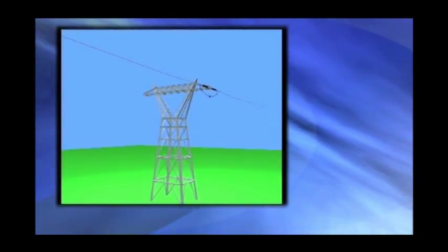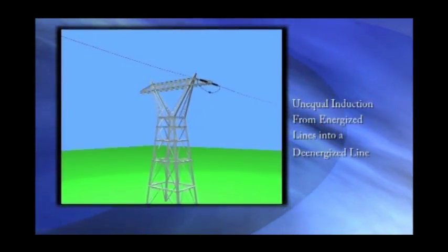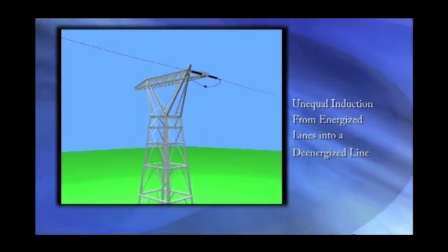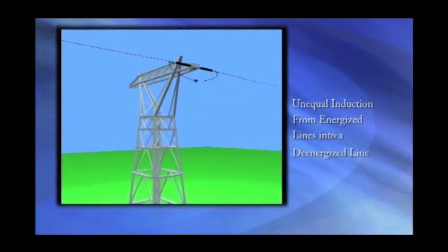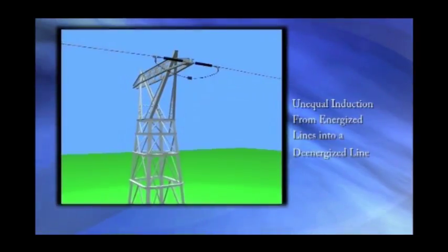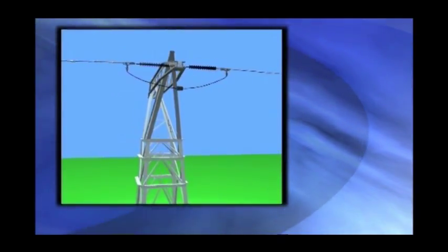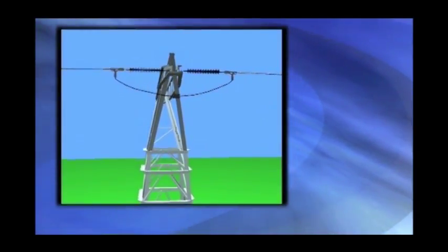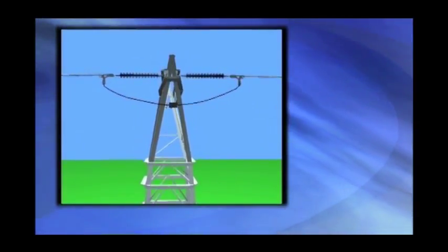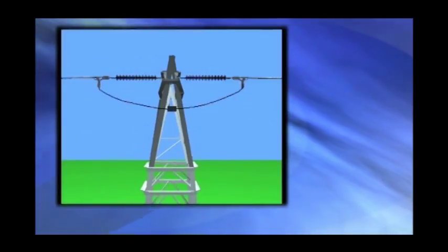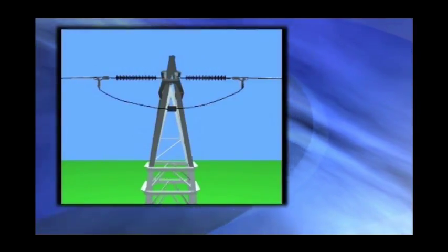This example is similar to example 1, but it is even more complicated and builds on the information discussed thus far. A crew is dispatched to repair a jumper on a dead-end 115 kV structure. The original jumper consisted of two ends of conductors, one from each side of the dead-end tower, that were bolted together with a clamp on a temporary basis to meet energization schedules. The task was to replace the temporary connection with a permanent compression sleeve.